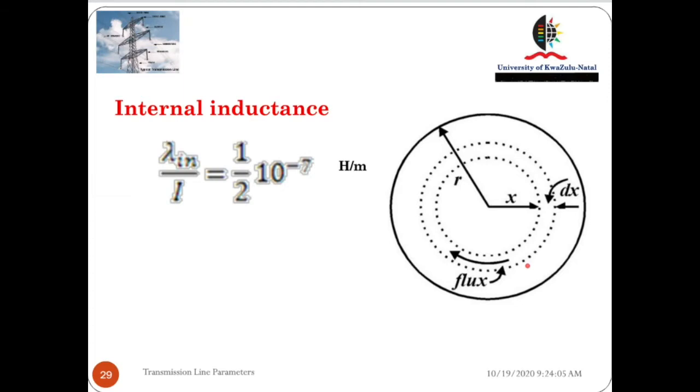Imagine now we are assuming that we have one conductor and we are allowing that conductor to carry a current of I ampere. How is that possible? It's not possible. We have to have a return conductor to complete the circuit of the current. But the return conductor is also assumed to be far away from this conductor that we are considering for calculation of inductance. So this is going to make that current distribution uniform across the entire cross section of the conductor, and it will do so.